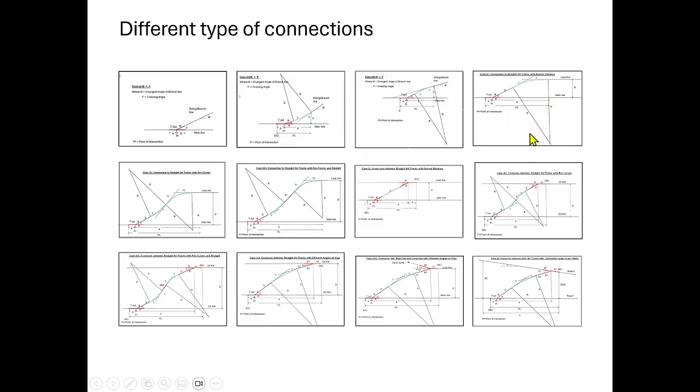Here is something about the connections between two parallel lines: the normal distance, a large distance, and still larger, and a crossover with the normal distance. Crossover means introducing two points and crossings on two lines, giving the connection, ensuring the through movement as well as the turnout movement on both lines. The same crossover with some large distance between the two lines, and still larger, how can it be done? Introducing a reverse curve with a straight. Here, parallel lines with a different angle of crossing. With this we can connect it.